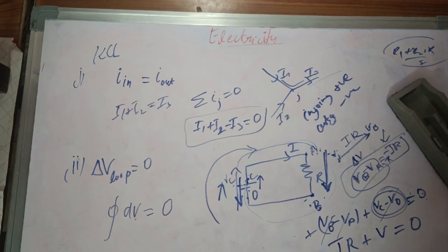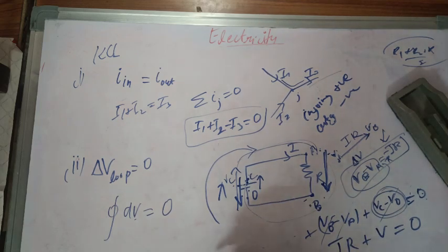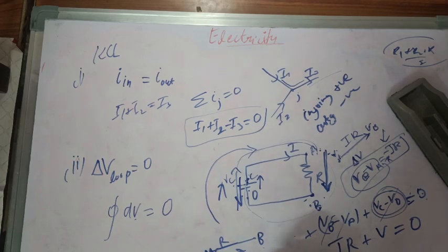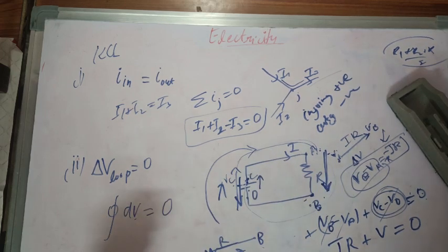So when I write the potential difference, if there is a point, let's say A, and a point B here, and there is some current flowing in this direction, then if I want to write VB minus VA, I will write it as minus IR. If I am taking V final minus V initial along the same direction as the current, then I have to take a negative sign with this value, because the current would be flowing from higher to lower, not lower to higher.